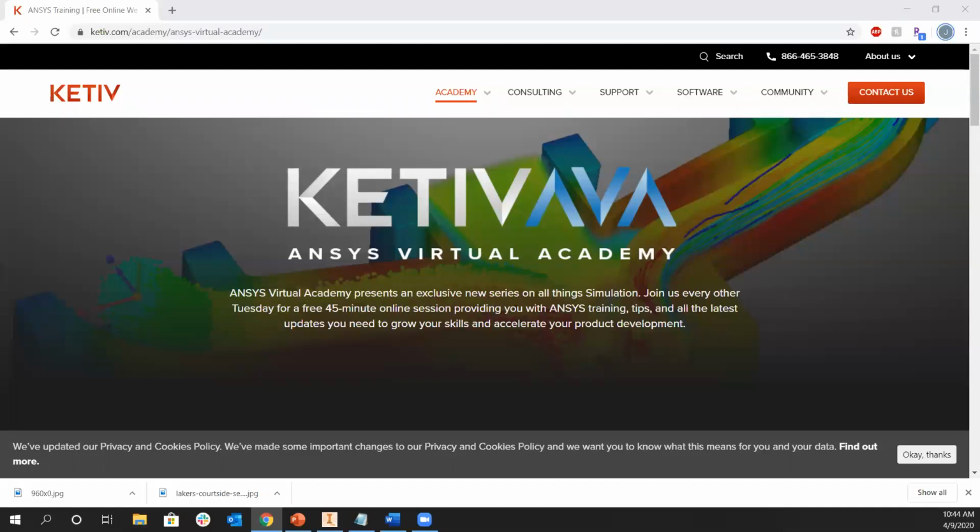All right, I see a question from Jeffrey coming in. He asked, when using iLogic parts with assemblies in the API, is it useful to insert them as iLogic assemblies, or would you recommend doing something different? So here on our team, if we write iLogic at a part level and you want the assembly level to understand it as well, you write another code that imports the iLogic that you have at the part level, and it'll understand it at the assembly level. That's what we tend to do 99% of the time, and that's always given us a lot of success. Yep, absolutely.